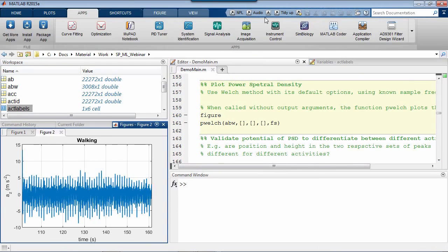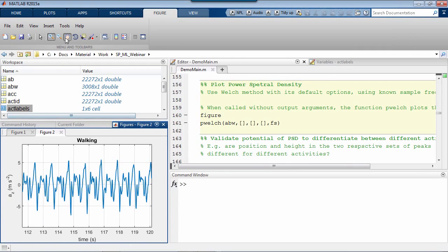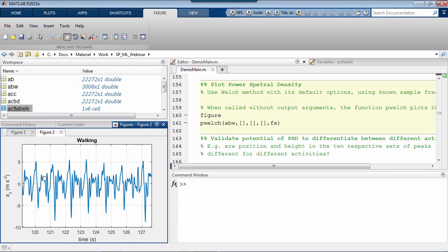We can zoom in and confirm that the signal oscillates fairly regularly, almost periodically. Now the question is, how can I measure how quickly it is oscillating, or some parameters to quantify the shape or fingerprint of these oscillations? A good answer would be by looking at the spectral representation of my signal, or some could say through computing its FFT. Much better than the FFT, which is a pretty low-level operation, the right phrase here is power spectral density. That may use the FFT along with a few other bits and pieces.